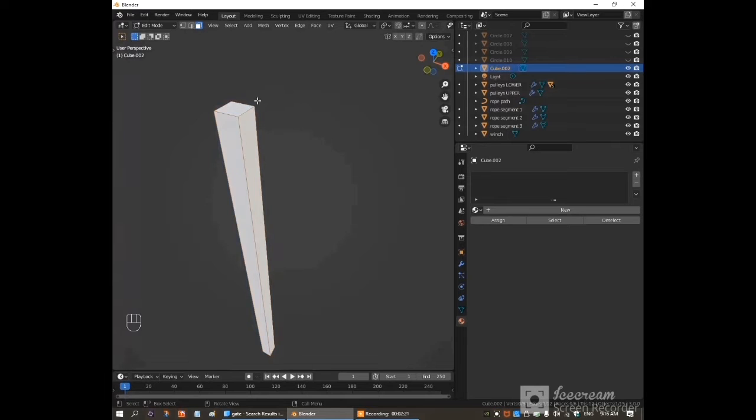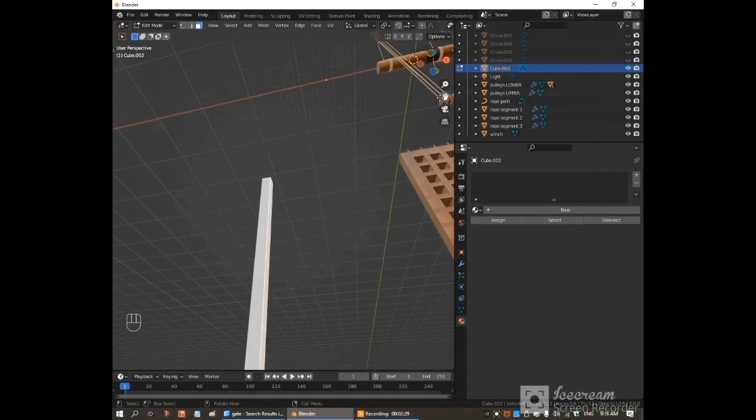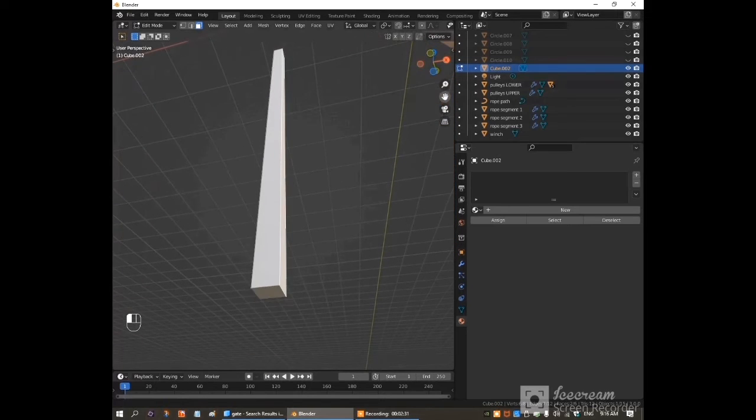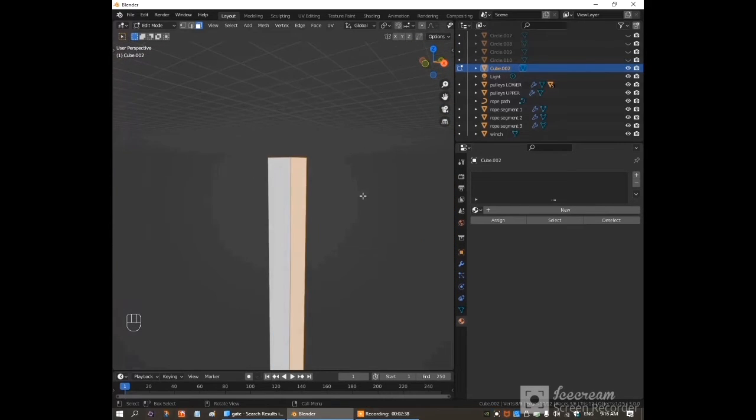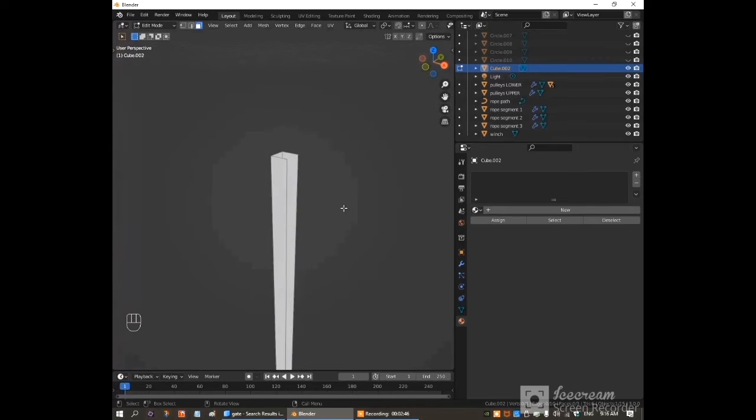And then I think you have to deselect everything. Go over here, and then now we're going to select this top face, select that, and then press shift and select the inside face. Then go down here to the bottom face and shift select on that one, and then let's just move it back to the top like this. And what we're going to do is we're going to delete those. Press delete and then delete faces. And you can see we deleted those faces.